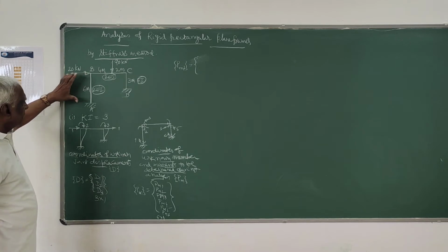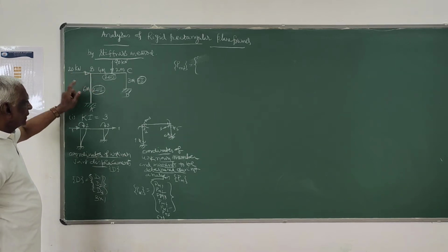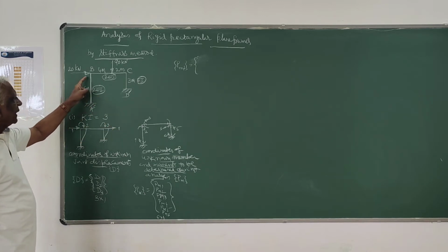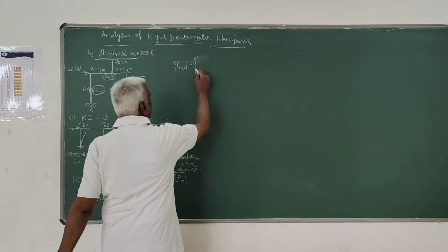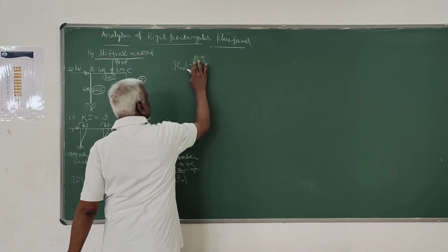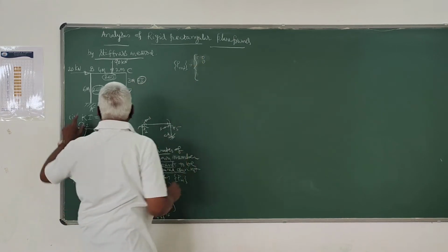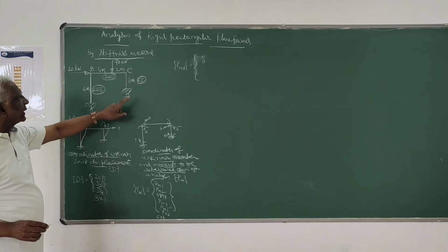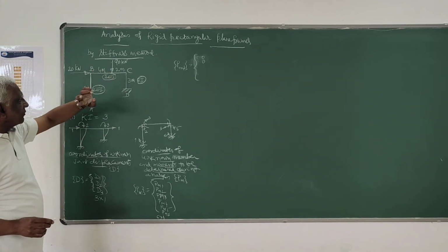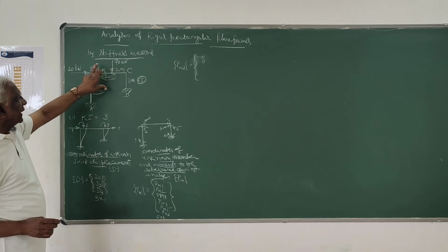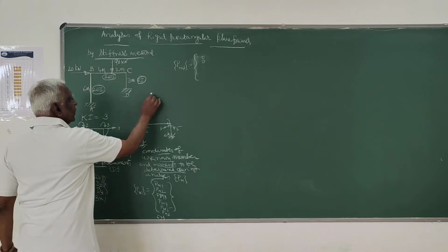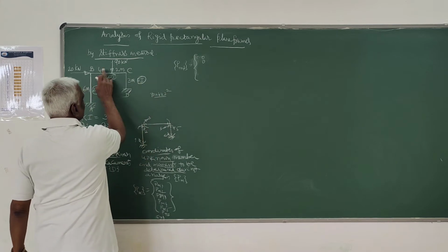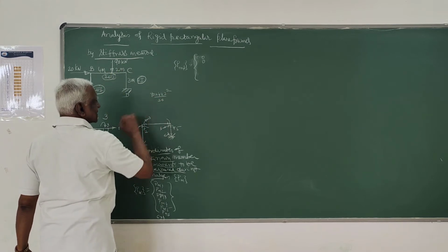So here on AB there is no member loading, so moments corresponding to coordinates 1 and 2, that's MAB, MBA, it is 0, 0, right? Then on BC, on MBC, that is corresponding to 3, it is W a b squared by L squared, that is 90 into 4 into 2 square divided by L square, that is 36.